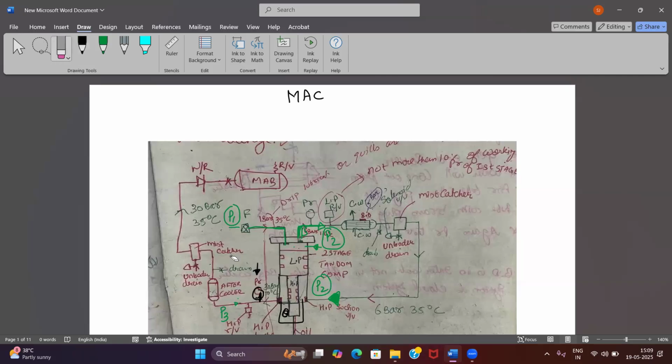Sir, for your pressure compressor, the pressure ratio will decrease accordingly if there are 3 stages. If there are 4 stages, then the first stage pressure will be lower, up to 30 bar. Pressure will further decrease, okay, because we have 3 stages to compress up to 30 bar. For your air cooled compressors, normally we use 3-stage compressors, and for water cooled compressors, the tandem type of compressor, we use 2-stage compressor, but with more number of units.